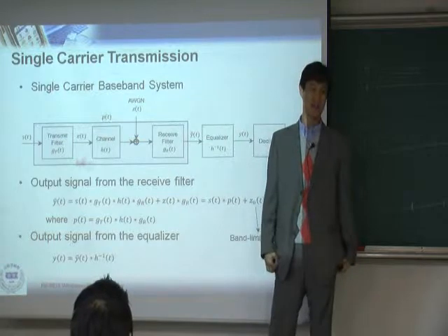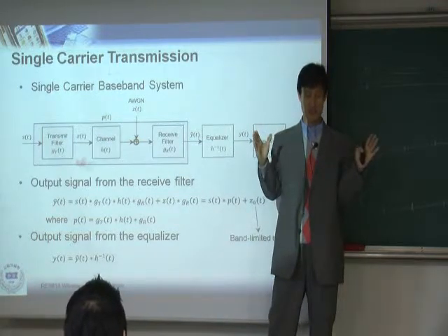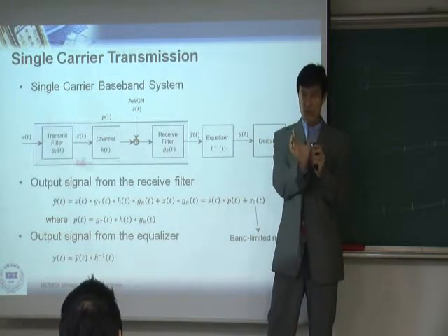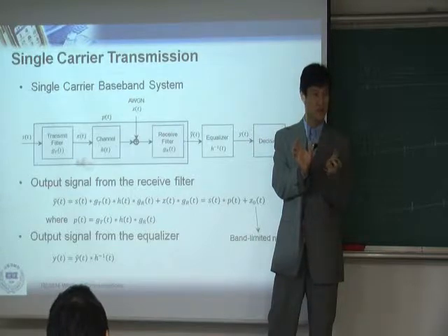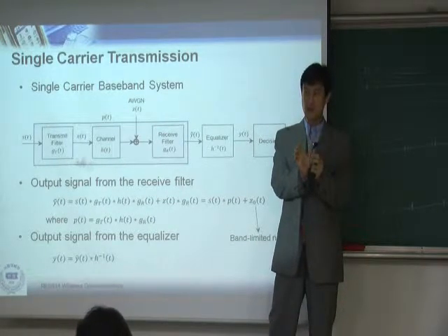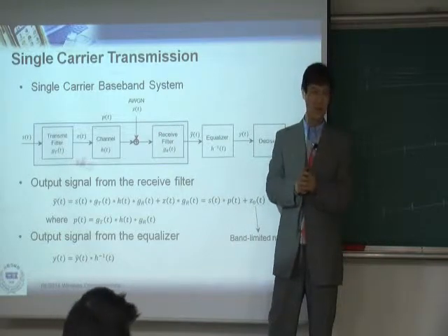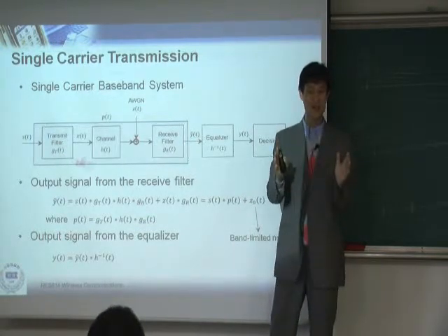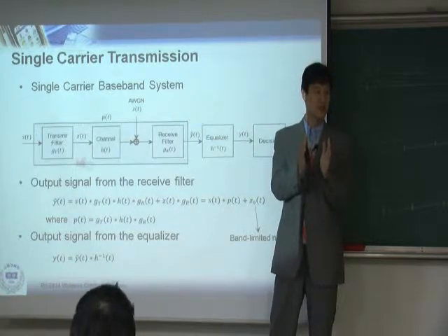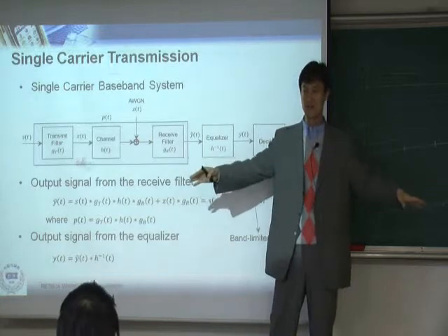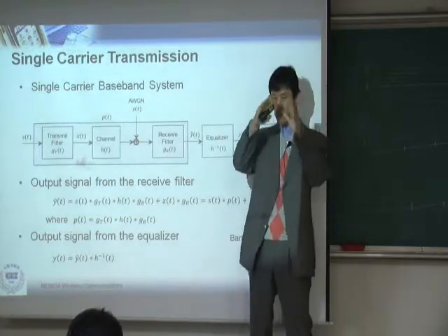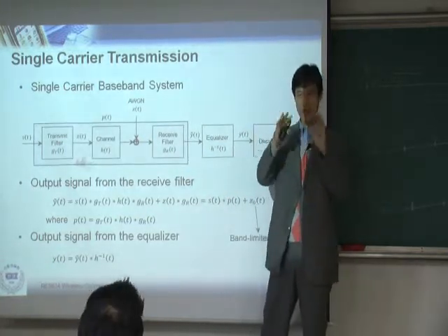That's very bad, right? Your spectrum has to be limited to a certain bandwidth, because sometimes that's the regulation by the federal agency, right? And also, you have to make it band limited, right? You are not allowed to transmit a wide spectrum. Therefore, you have to make a sharp tail. You have to make some nice spectrum.